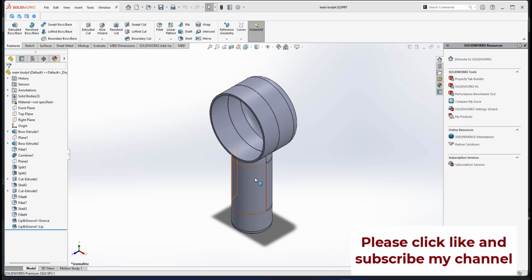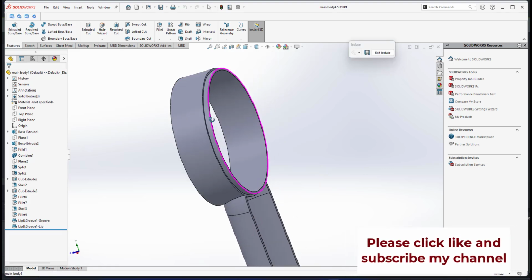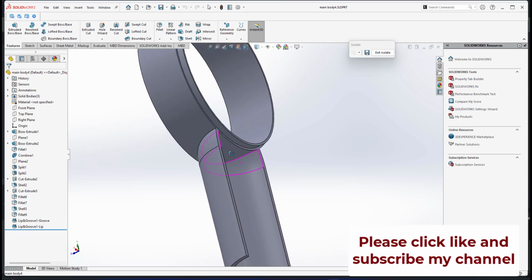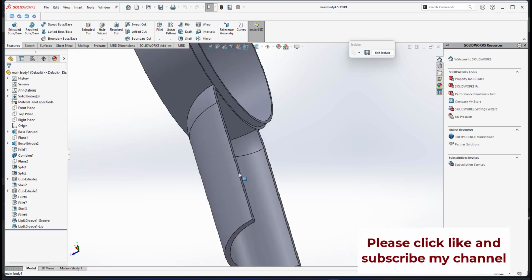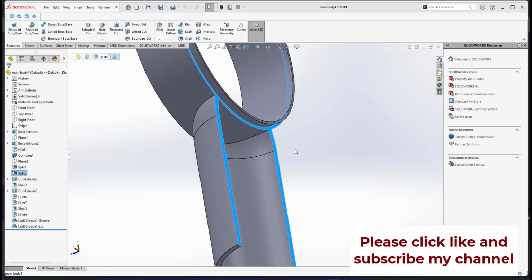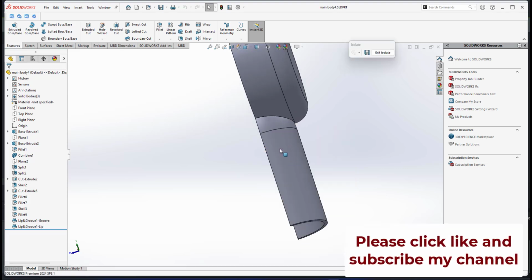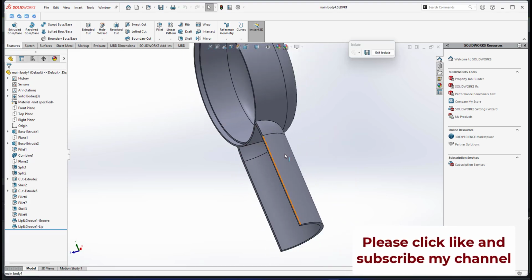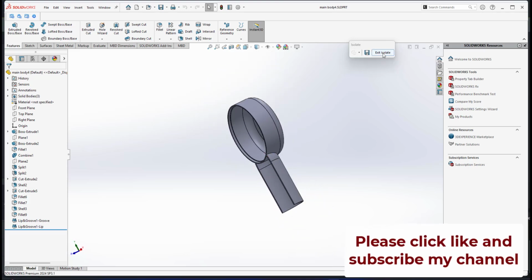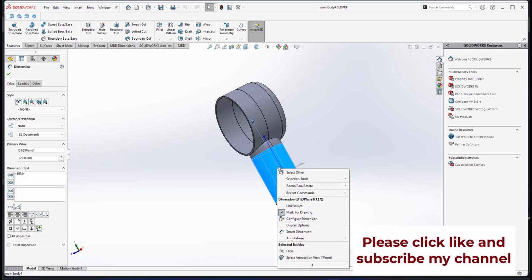The next move is, if I isolate again this front part, the blower unit, I've just created the lip. But if you look at the handle here, we have a flat surface here, so it's connected to the rear part of the handle by this flat surface. Actually, it's not supposed to be like this. You have to put another feature like I've shown you, lip and groove. But I found out, let me isolate this front and the rear part.